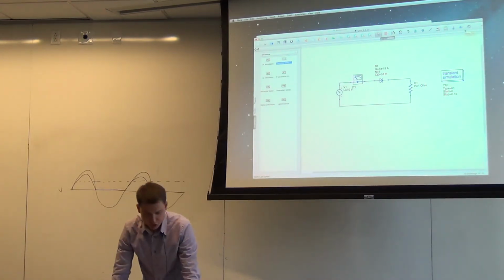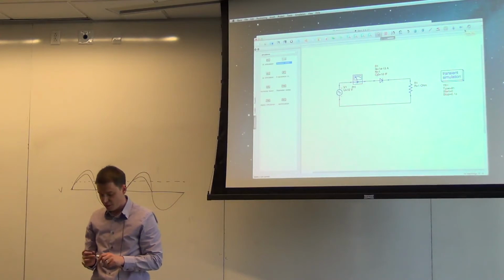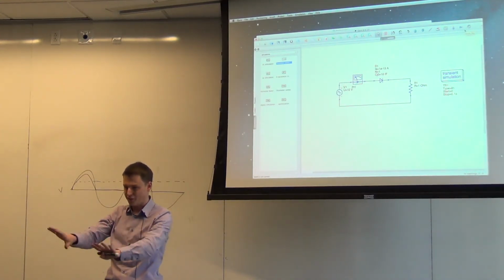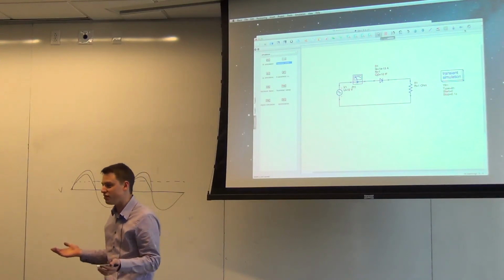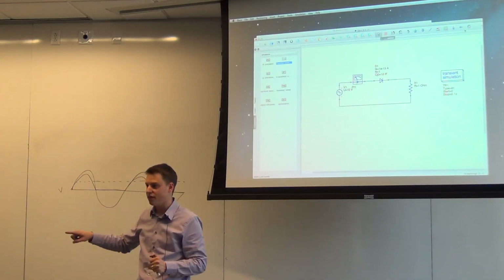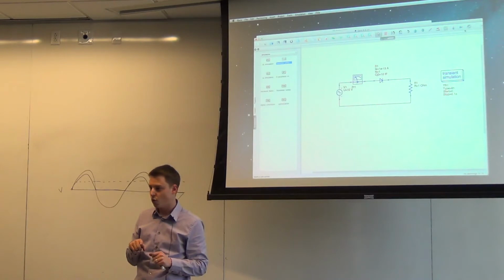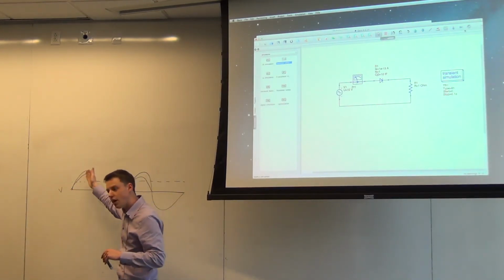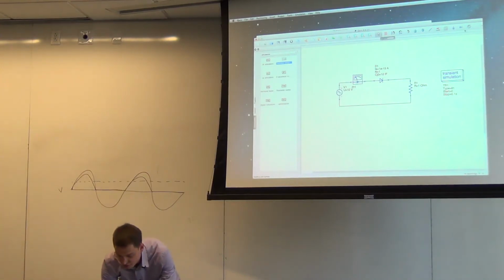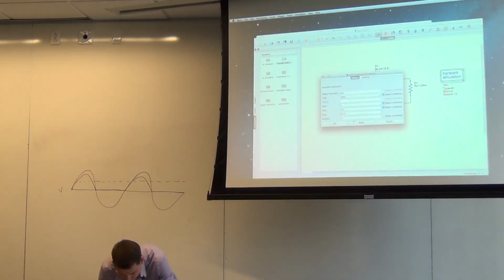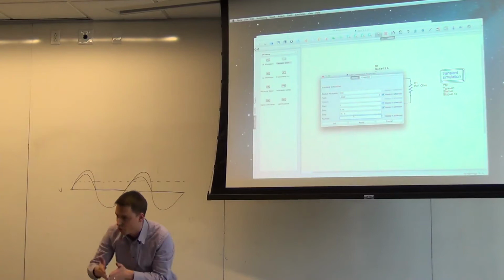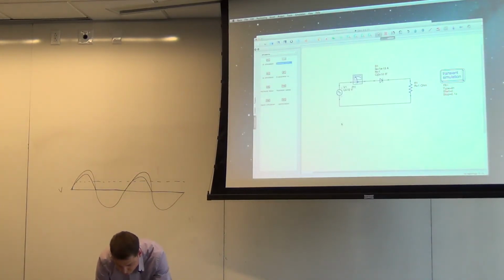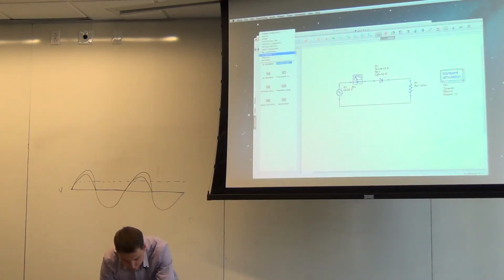So what the transient will do is, AC and DC simulate what is the steady state voltage and current you get from this thing when you let it settle to whatever it is. And for AC, that's actually easy because every single sine wave is the same. Here, they're actually different. And so what it does is it gives you a plot like this, where for every time point at some fine resolution, and actually I need to step up. One thing I have to do is, this is essentially the number of simulation steps you get. So let's say it's like 1,000. It might be too many. We'll see if that actually works or not.